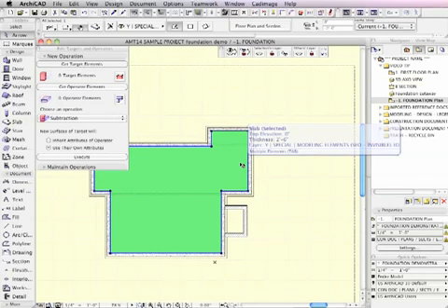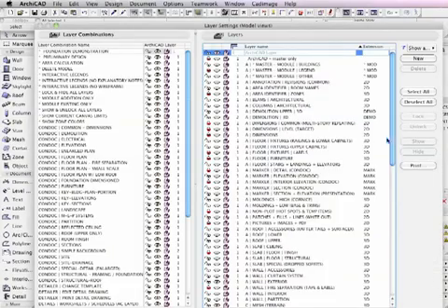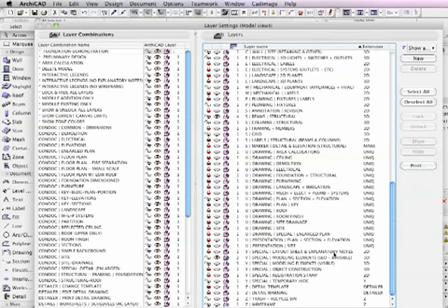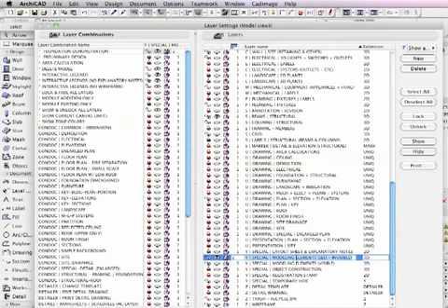That is on a special layer called Y Special Modeling Elements SEO Invisible 3D. If I open up the layer dialog box, you'll see that this layer, which is for elements that are for modeling purposes but are normally invisible, has been put into a special wireframe state. If I click here, you see that's solid, that's wireframe.